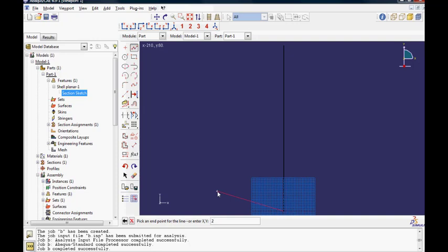The width of this plate is 2 and y 0, and then let's have it slightly to the side with a value of 0.1 millimeter. So let's give x 2.1 millimeter, y 500, x 0.1 millimeter, y 500, and go back to 0, 0. Done.